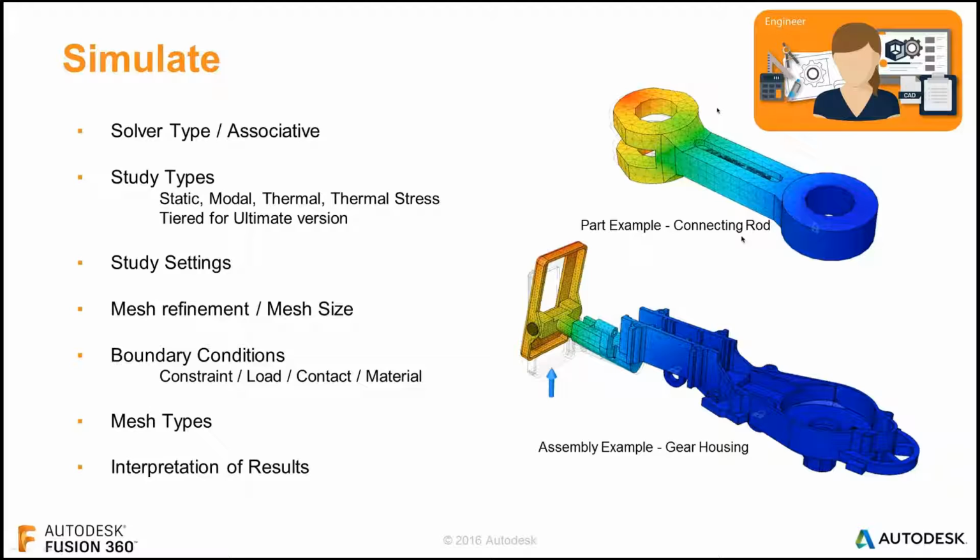When you get into those advanced simulation types, you no longer have the option of doing a local solve. For static, modal, thermal, and thermal stress, the core simulation types, you have the option to do a local solve or a cloud solve. The more advanced simulations have to be done in the cloud, so people need to have cloud credits available. Though frankly, for what's being done, it uses a pretty minimal number of cloud credits.